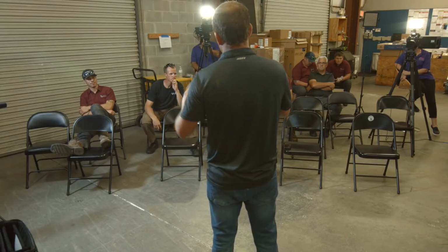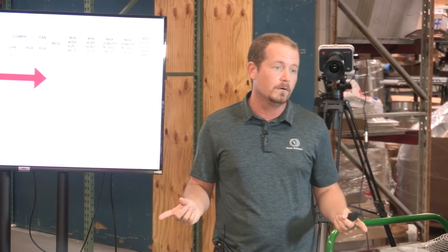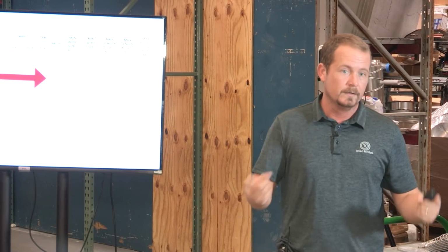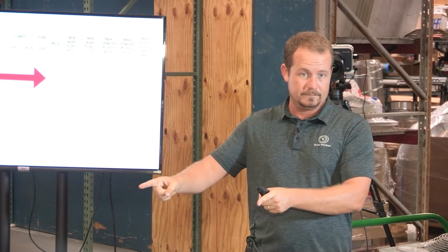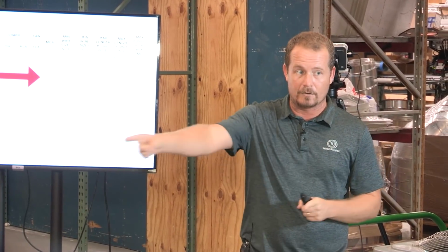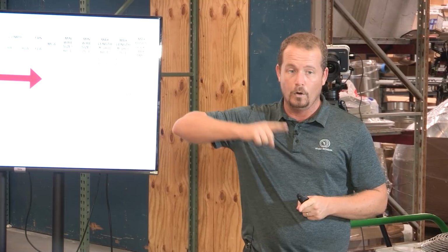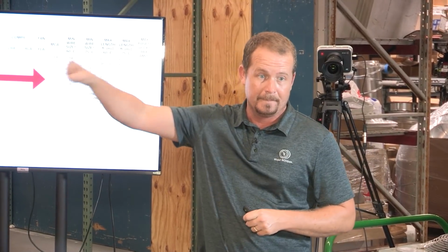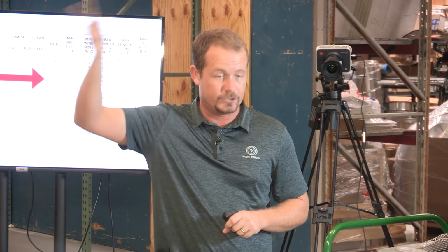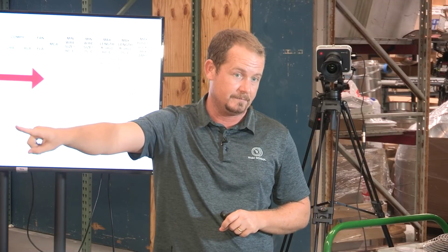It's safe because of what electricians learn since they were little babies, because it's actually a really good thing to know. It is a good rule. The breaker protects the conductor, right? So at that point, it doesn't matter what you hook up. If you exceed that 15 amp rating for any amount of time, it's going to trip. It's going to trip before the conductor is compromised.